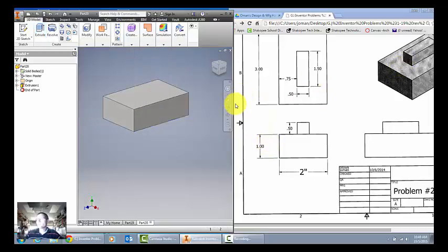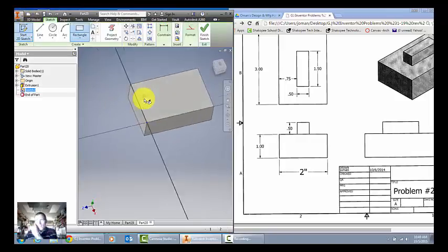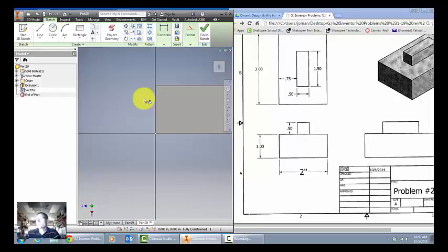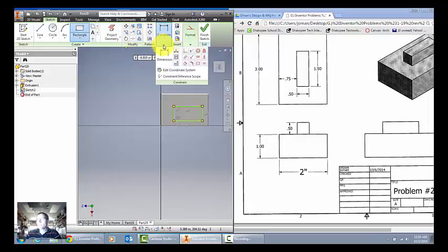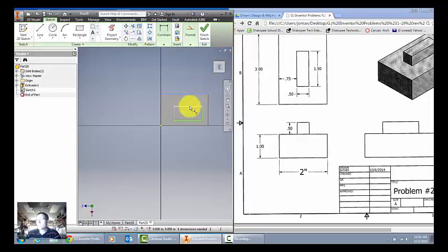Okay, now the upper part, we're going to draw another sketch for this. We're going to put it on the top. Rectangle in the middle. Again, this is a guess right here. Okay, notice I'm not even close to being correct or spaced out right. You can fix that using the dimension tool. So I hit dimension. I'm going to click here, double click there, and another click. So that was about 4 clicks to get that in place. It says it's 0.75. We'll get that line moved over.